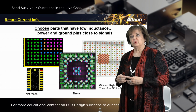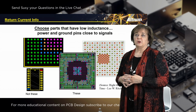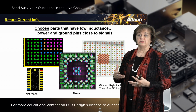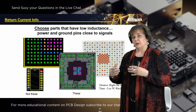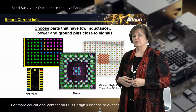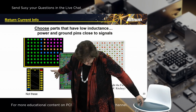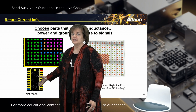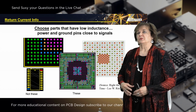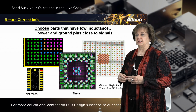When we are dealing with the return current, we need to think about the parts that we're selecting and putting on our boards. If we don't have any control of that because somebody else is making those decisions, then we need to at least share our information as to what we believe we understand about the way the parts work and don't work. For example, the part down here has worked for many, many years. It's a typical SOIC pattern with the power and grounds in the opposite corners. And it worked great for many years when we did not have the really high-speed signals.